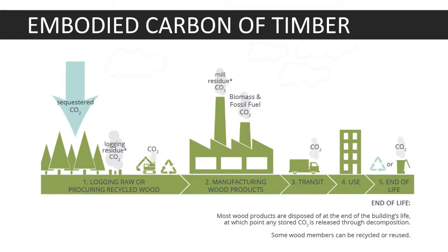Now, timber can have an overall embodied carbon which is negative in some cases. The thing is that trees absorb CO2 when they grow, and we talk about sequestered CO2 in this case. The manufacture of wood products can, however, emit some CO2, but the overall bill of CO2 tends to be much better than that of concrete.